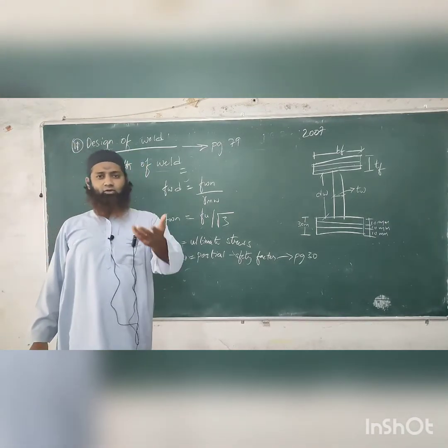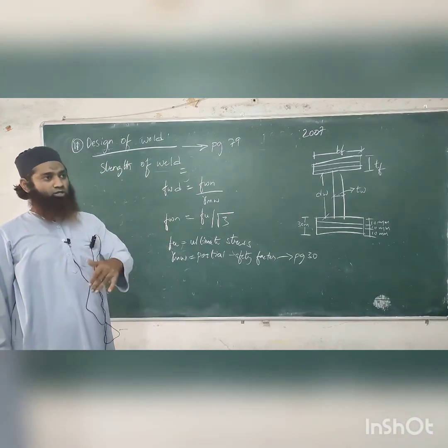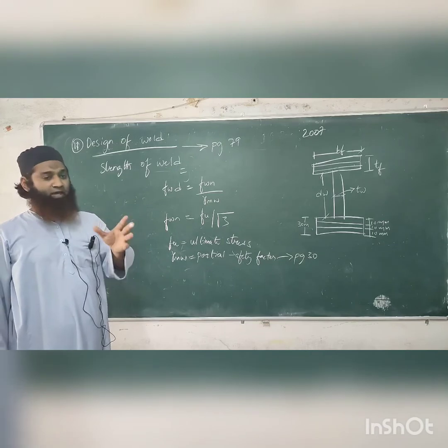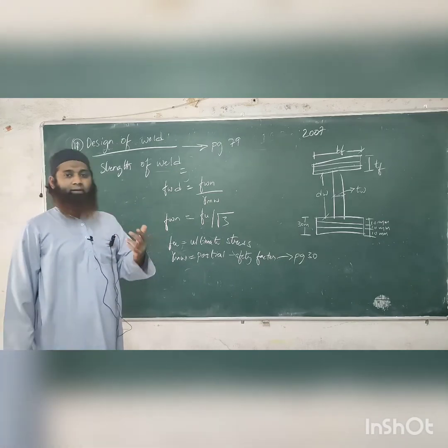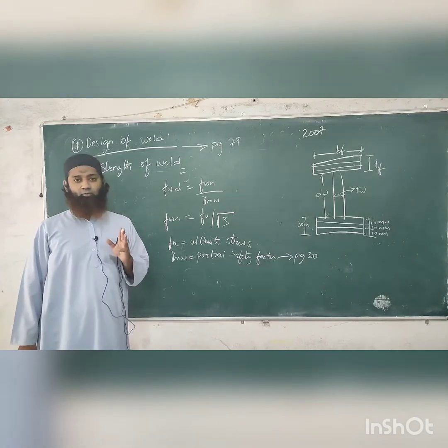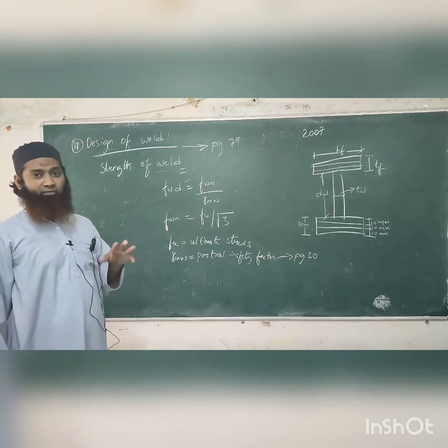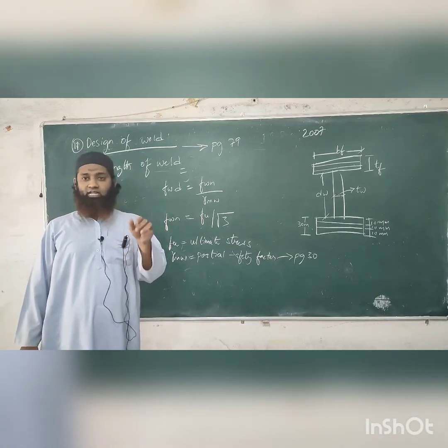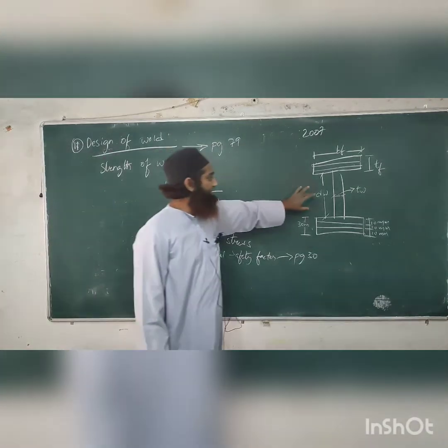Now I'll just tell you a short recap. First step was seeing what loads are coming onto the girder, and the span of the girder. Next we were determining the shear force. Step 2 was determining the maximum shear force and the maximum bending moment. Then we came to design of the web. We determined the depth of the web, DW, and the thickness of the web, TW.